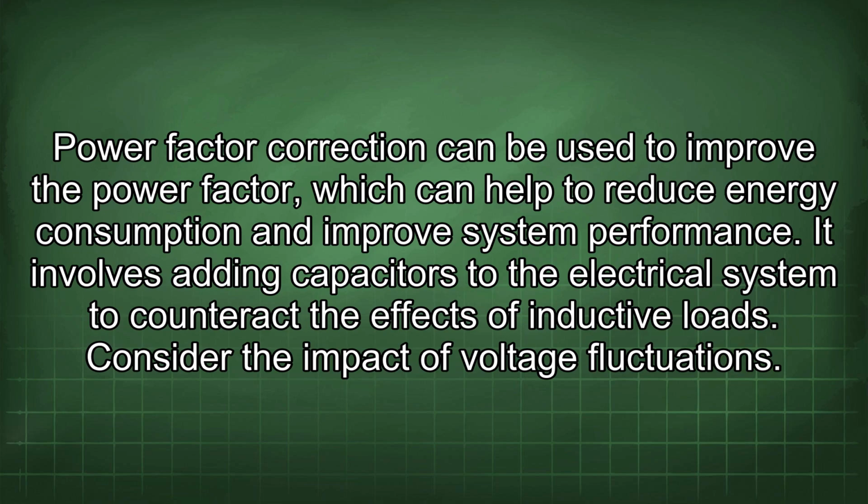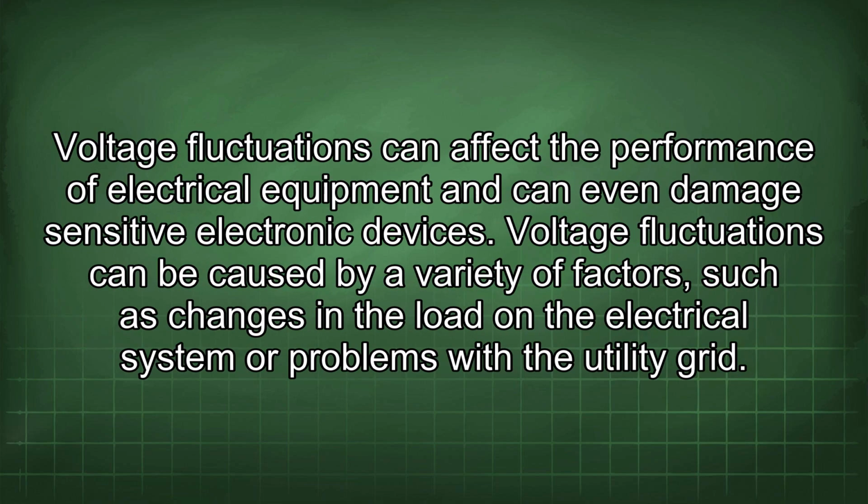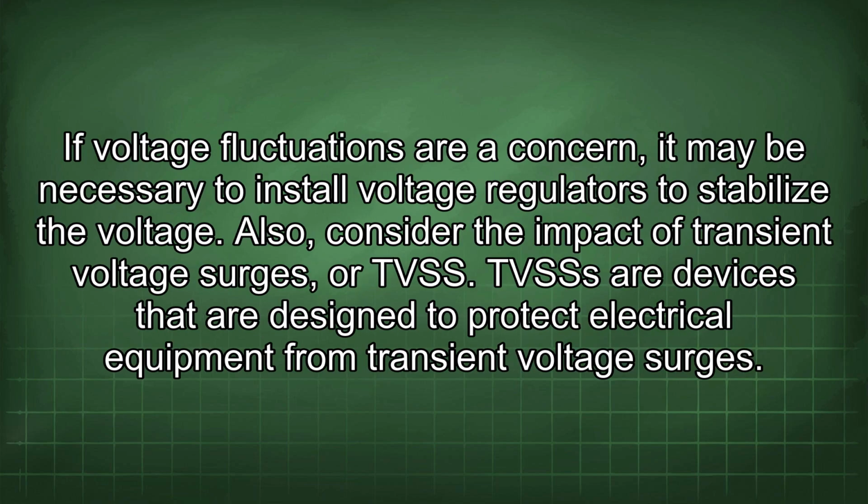Consider the impact of voltage fluctuations. Voltage fluctuations can affect the performance of electrical equipment and can even damage sensitive electronic devices. Voltage fluctuations can be caused by a variety of factors, such as changes in the load in the electrical system or problems with the utility grid. If voltage fluctuations are a concern, it may be necessary to install voltage regulators to stabilize the voltage.